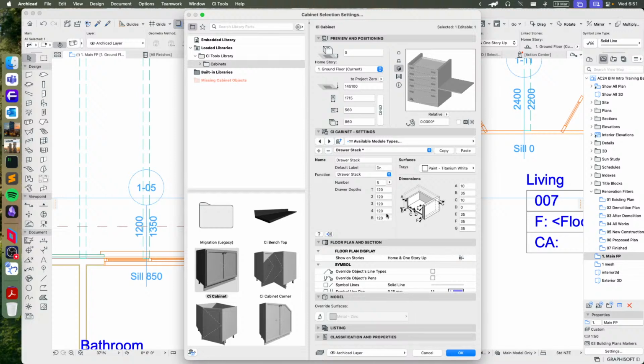In this case, because our actual height of our cabinet is taller than that, the bottom piece is actually stretching out to fit the size of the height that it has available. But we can define those heights here. So we could say that actually drawer number 3 should be 200 high. And you'll see that that now does that. So you can set those to whatever you need them to be. And then you can set the dimensions for the actual drawers individually each as well.